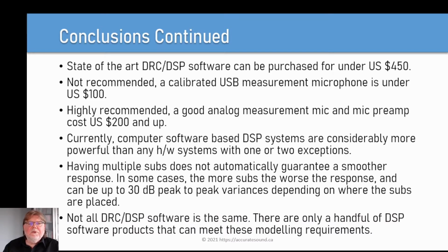Conversely, software with FIR filters has a graphic slider at every 0.7 Hz, so more than 100 sliders below 100 Hz. The other issue is that IIR filters are being used below the transition frequency, which does nothing to correct the non-minimum phase behavior that's in the room. IIR filters can smooth the frequency response, but no time domain correction. So only half the transfer function is being corrected. Remember, we're talking about state-of-the-art here.